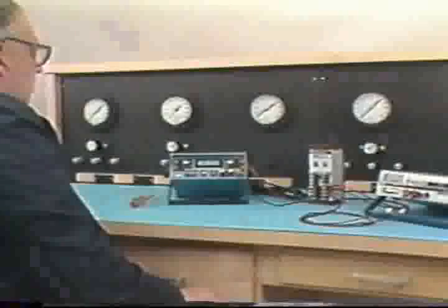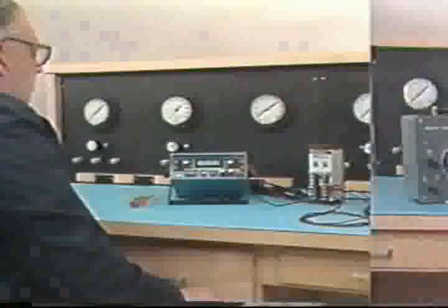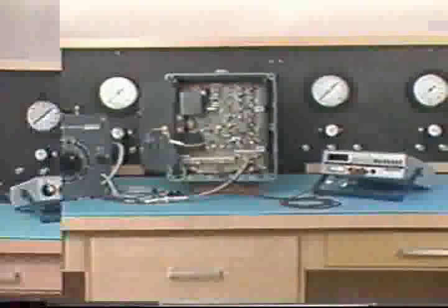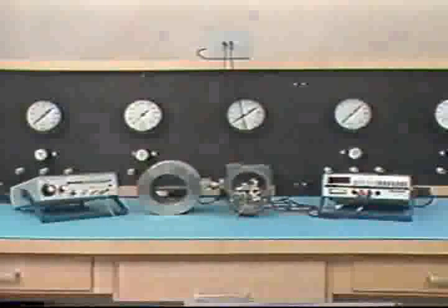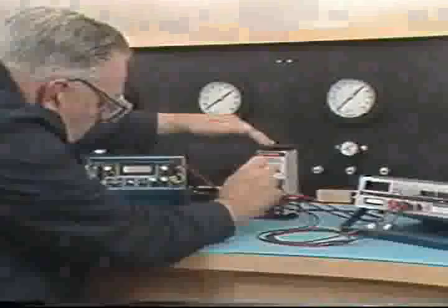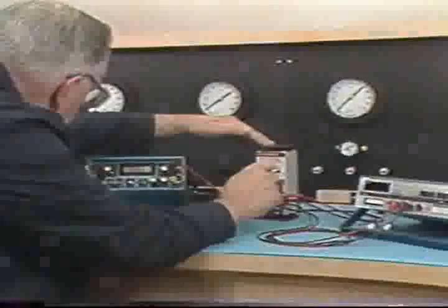In this program, we'll look at instruments used to measure two kinds of process variables, flow and level. We'll see that although these instruments may operate differently, they are calibrated following the same basic principles. Instrument calibration should include setting up with the appropriate input and output standards, applying test inputs at several points in the instrument range, identifying the errors revealed by the tests, and finally, adjusting the instrument to correct the errors.